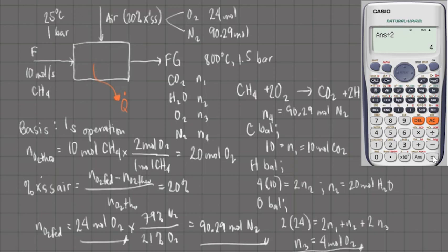So what's important here is we now have finished the material balance and we have determined the amount of moles of all of your substances in the reactant and in the product. Our reactant streams are both the fuel, F, and the air, which consists of methane, inlet oxygen, and inlet nitrogen. While our product stream contains 4 components, that is carbon dioxide, water, excess oxygen, and excess nitrogen.